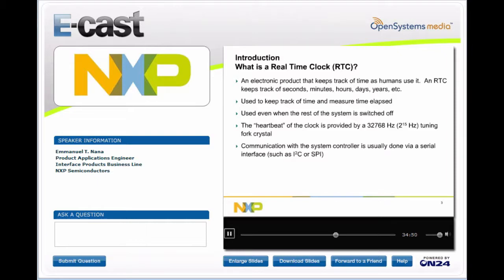Because these devices consume as low as 100 nanoamp, even with a device that has just 5 microamp hour, the real-time clock can last as much as 50 hours there. So that's a lot of time. And now, if you use something that has even a bigger capacity, then you get even more time out of that.